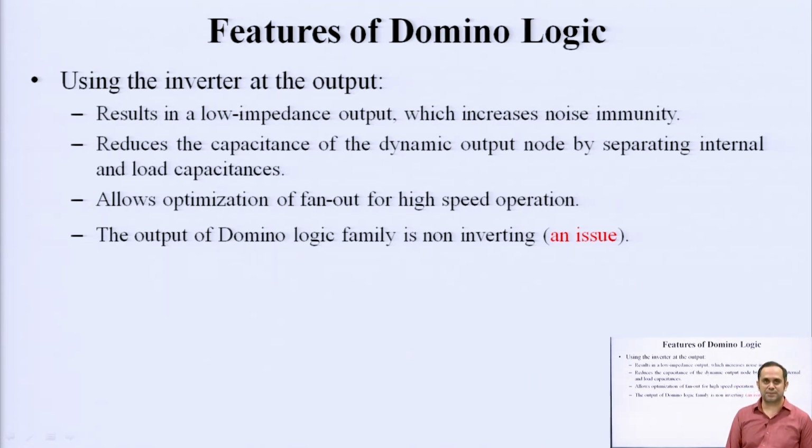from the design aspect. The universal logic gates are NAND and NOR, which are inverting in nature. When we do any CMOS design, we basically are designing an inverting logic circuit. So, you first design the NMOS pull down network using your NAND or NOR gates using inverting logic, and then use a complementary version of that in the PMOS circuit. So, if you have a series connection in the pull down network, you would replace it with a parallel network in the pull up side and vice versa.